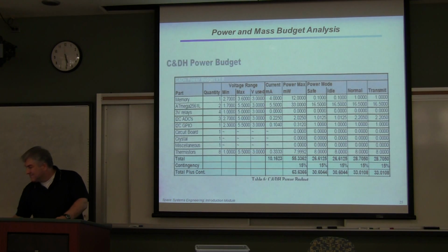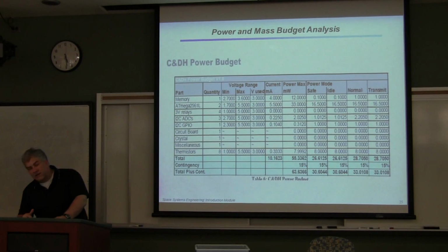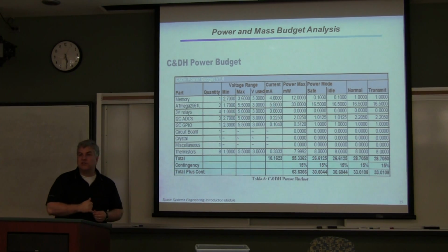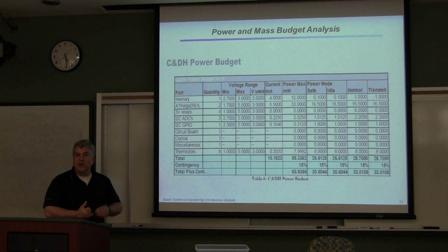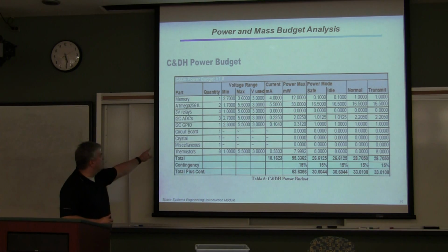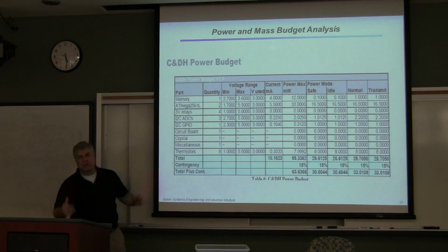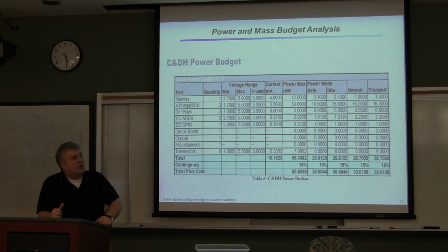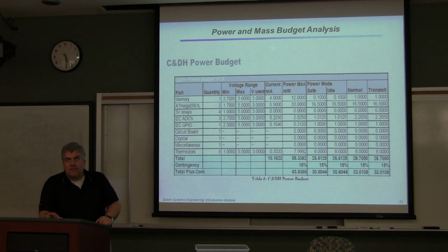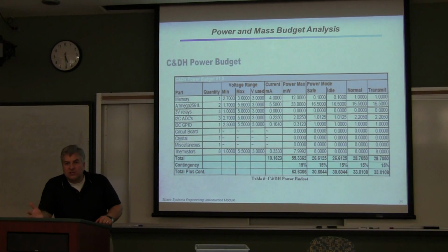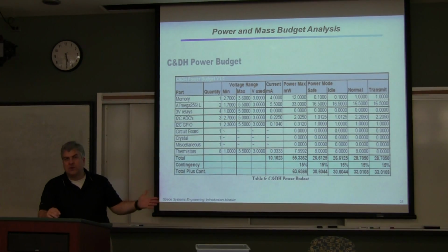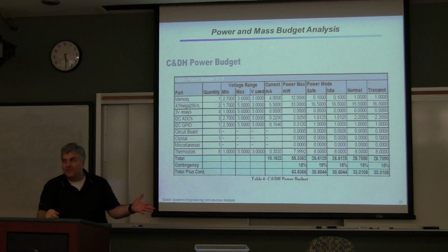Yeah. Okay. Oh, here's an example of the power budget. I actually have used this with cell phones, where we had to identify something. In fact, we had one situation where there's our processor up here, and we were using an ARM processor, and it turned out that we had to identify: do we speed up the processing of the phone and consume more power, versus go to a new part that costs more, versus keep it running slow and not being able to handle everything.